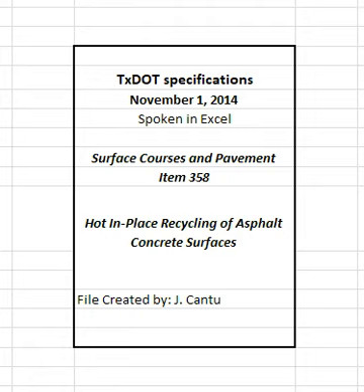4. Construction. Rehabilitate existing asphalt concrete pavement to meet the typical sections shown on the plans and the lines and grades established. The existing pavement should be heated and milled to the required depth of treatment as shown on the plans. 4.1 Certification. Personnel certified by a department-approved hot mix certification program must conduct all mixture designs, sampling, and testing.